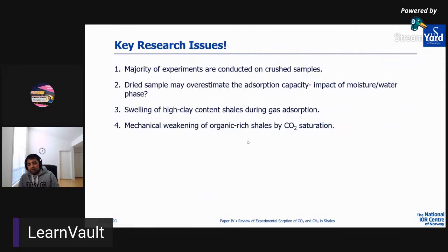But whatever research is being done in this field for CO2 injection in shale gas production for enhanced recovery, there are some limitations in all the research currently being done. From an experimental point of view, the majority of the experiments are conducted on crushed samples. Since shale gas has very small pores, it would take a long time to perform experiments on a real core from the reservoir. So they crush the samples and pack them into a core shape again, and then they perform the experiment.